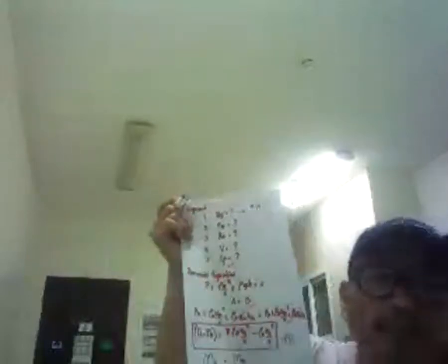Substitute na siya, no? PA. We should use this equation 1. PA, 300,000. Minus PB is equal to density B, 1,000, UB, nakuha na siya, 10 raised to the power 2 divided by 2, minus density A, which is just the same, 1,000. UA, in our drawing, we have a velocity that's coming in, which is 5 meter per second.